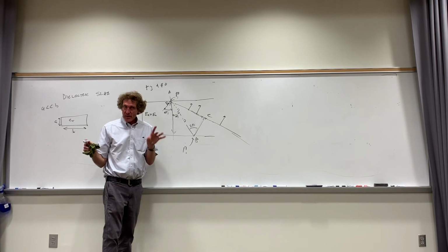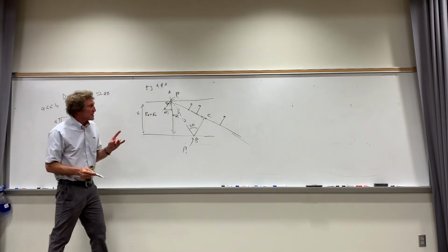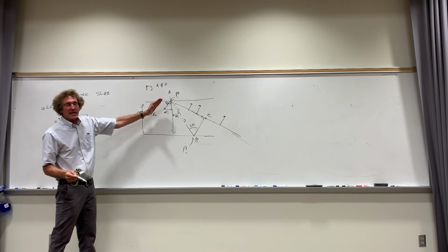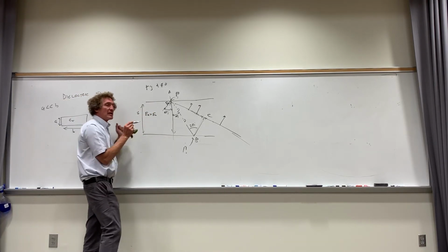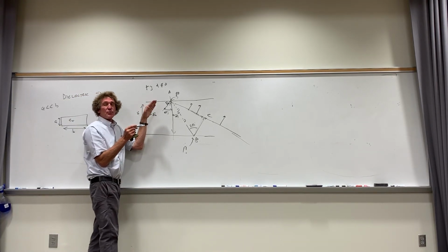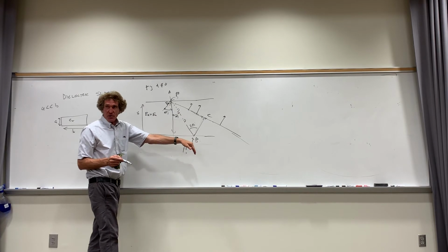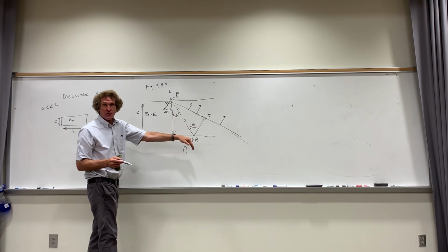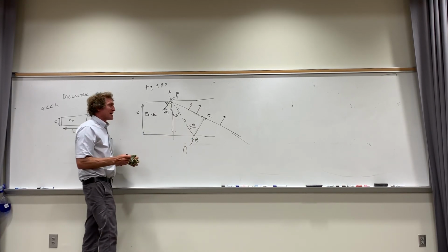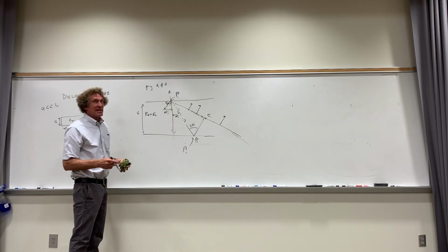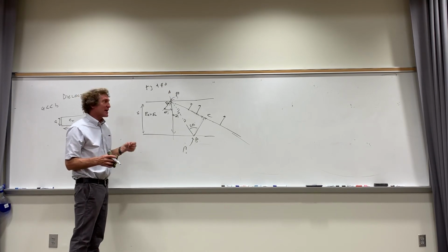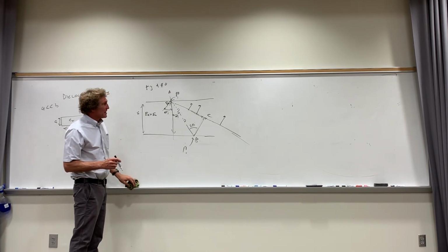All right? Now, the other thing is, this guide has to operate at an angle such that this angle is equal to or greater than the critical angle. Remember, the critical angle is what? The angle where everything bounces back. Do you all remember that, class? Everything bounces back. There's no transmitted power. So nothing goes in that direction, basically. So here's how we go about this.